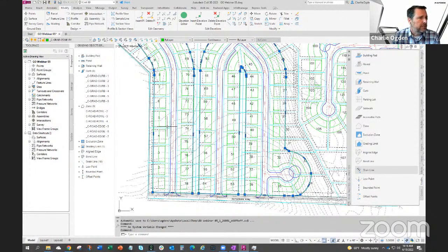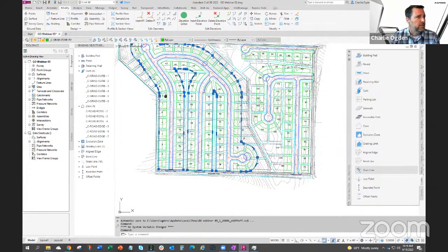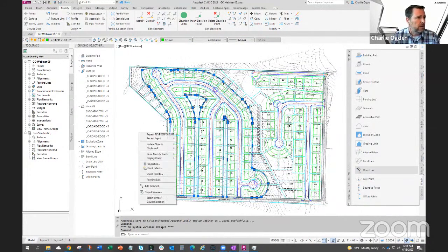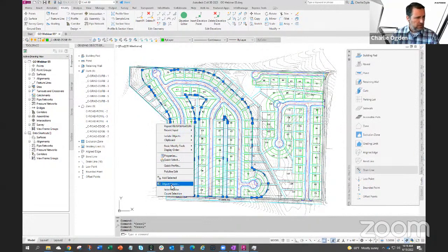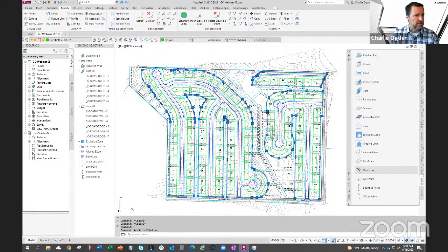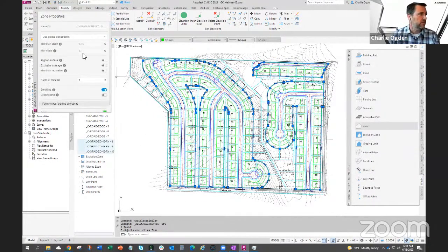And also we want them flattened out. Where we're going to put buildings, just kind of flatten out. We can tweak this a little bit after we have our roads done, but for now, we're just going to add some, it's kind of a smaller slope in this area. So I'm just going to select, I have kind of a yard zone around each roadway. And I'm just going to add these as zones just to flatten them out. So I'm just going to go 2 and 5.